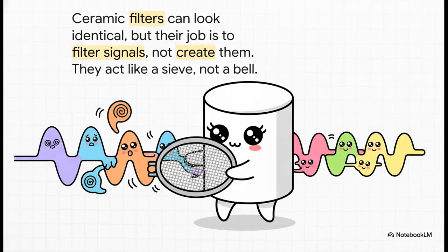And just to add one more little wrinkle, be careful of ceramic filters. They can look almost identical to ceramic resonators, but their job is completely different. They act like a sieve, right? They only let certain frequencies pass through while blocking others. They filter signals. They don't create them.